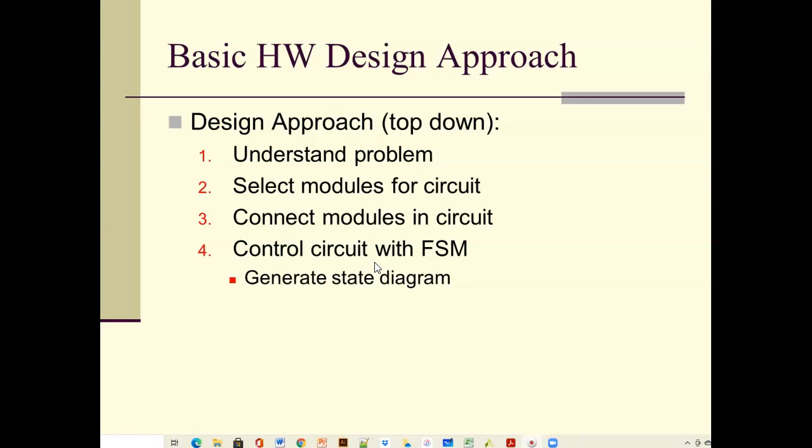The next step, once you get all the modules you think you need for this thing, is to connect them up properly, and then you need to control the data flow through those modules, which is going to be done with the state machine. So the state machine is going to be reading the various status outputs of your circuits and then issuing the proper control signals.